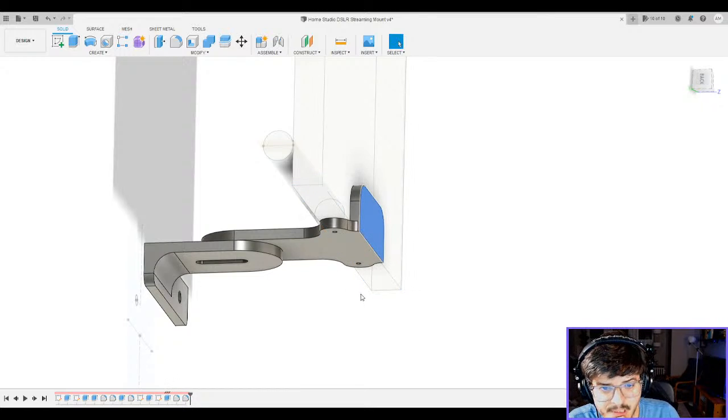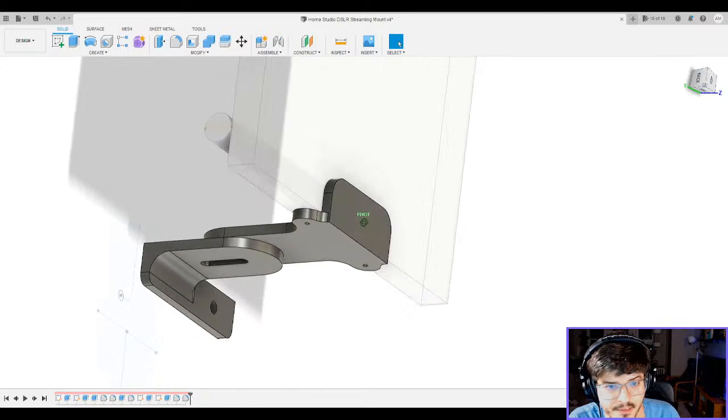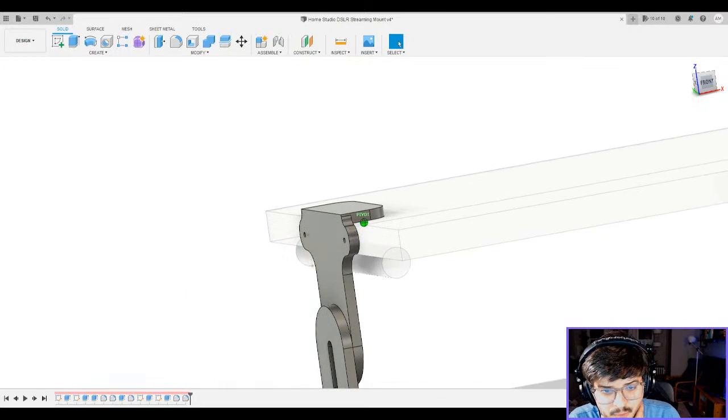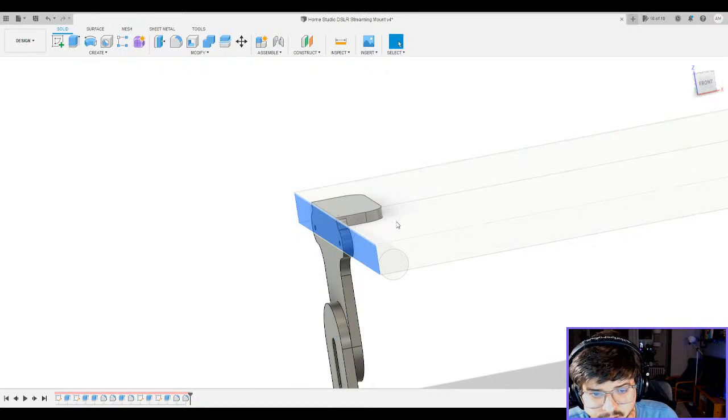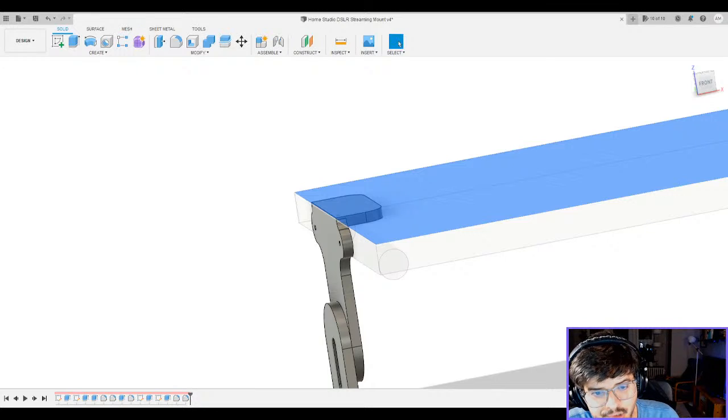This is really just meant to stabilize everything. What I would really like to kind of see is a rib on the outside here. So like just a bulge. I know it sounds weird, a bulge, but like a bit of mass right here on the back end to kind of give it a little bit more strength. But the problem is it has to print on that side, and I need to keep this right angled so that it actually latches on to the shelf.